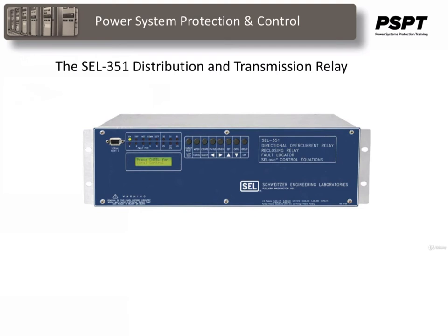This protection IED is capable of managing a complete low voltage feeder protection system, complete with single or multiple shot automatic reclosing. As with most protection IEDs, the relay is also capable of logging sequence of events, fault oscillograph records, online metering, and distance to fault location measurement. So it does a lot more than the old school relays, and they are just getting better and improving more.